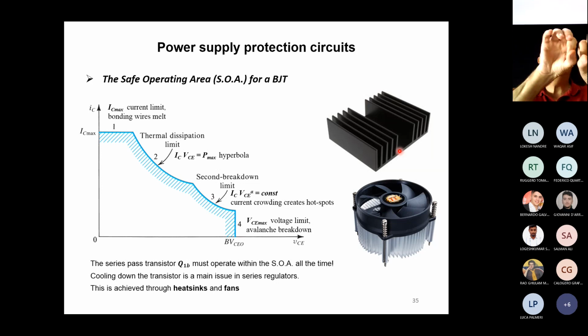Heat pipes are tubes made of copper, inside which there is some liquid that basically evaporates when it's on the chip, navigates inside the pipes, and the fan is somewhere else. For instance, the chip, the CPU, is here, and the fan is here. So these heat pipes bring the heat from here to here. It's like a sort of small air conditioner. It's working on the same principle as air conditioning without having a pump. Or rather, it's a pump which works by itself, okay?